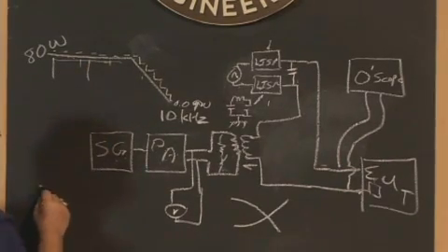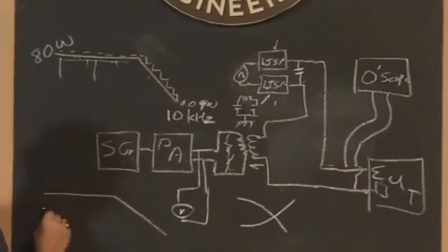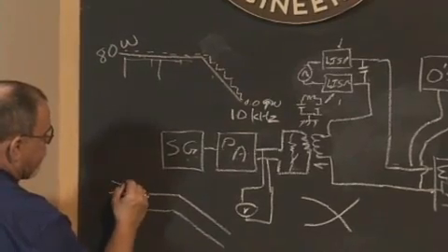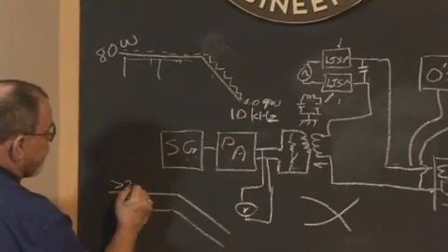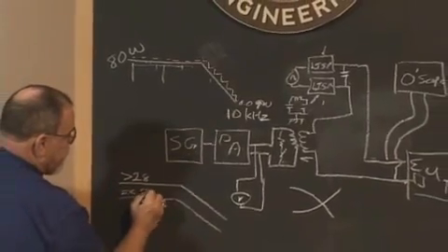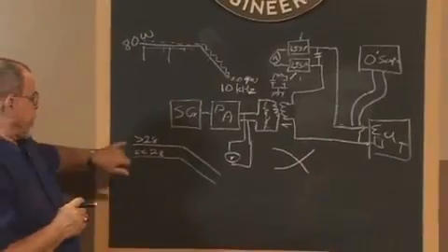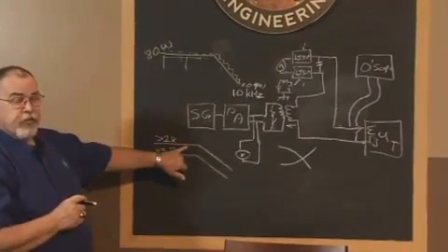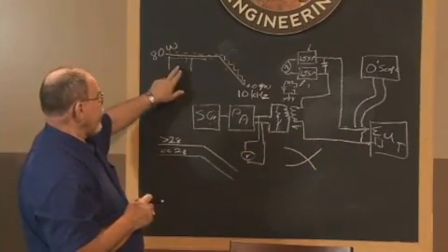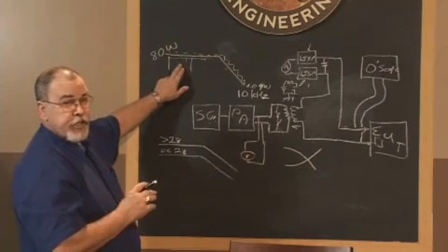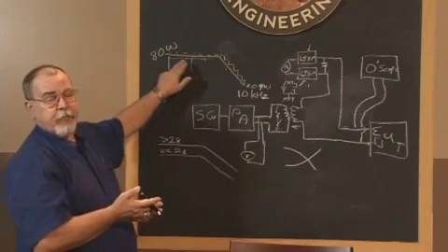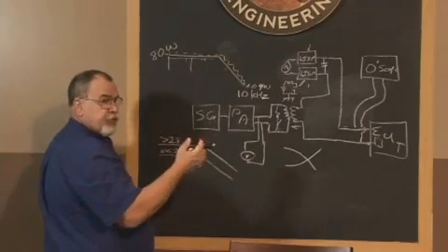A test limit is a similar type line, and there's a couple of them in the standard, and I think it would be greater than 28 volts and equal to or less than 28. I believe those are the two curves that appear. So this voltage is our goal, our test voltage. So we try to measure the test voltage appearing here. If we get to where the pre-calibrated settings were met, then we consider it compliant as long as the test article is behaving. So two curves going on.